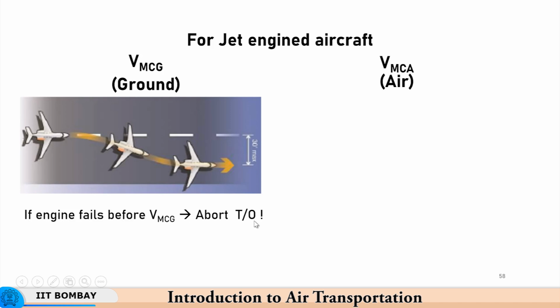If you have a multi-engine aircraft, suppose two engines for example, and one engine fails, you are left with half the engine power. With half the engine power, you really cannot run the aircraft to its full flight envelope. So, you will have to do certain maneuvers and then come back and report that the aircraft is okay.